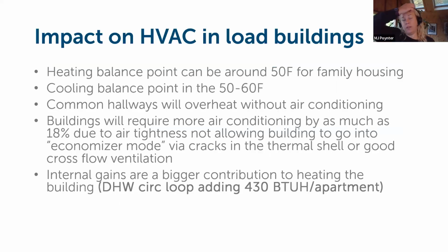When designing with super insulated walls and really well done air tightness, we're finding that the balance point, the point at which you go from heating to cooling, which oftentimes is not an exact number because you've got a buffer zone where you don't have heating or cooling, is being pushed down for heating. Normally, you would see something around 55 or 60 when you would start needing to heat. And now we're seeing it at 45 to 50, which is much lower than you would expect.